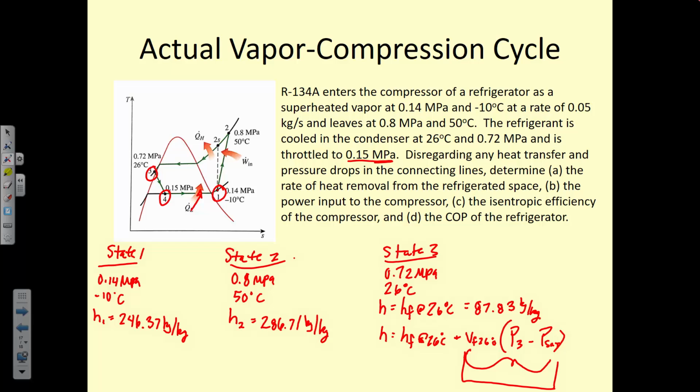Now, if that's really far, like if we see that the saturation pressure and our given pressure is pretty far away, you want us to use this correction factor? Yeah. Like in the last homework, problem 2, homework 5, it was like 15 megapascals. Nobody used the correction factor. Very few people used the compressed liquid table. They just used the values from the regular table. So that led to a lot of errors in calculating that enthalpy at state 2 or something. So be careful about that.